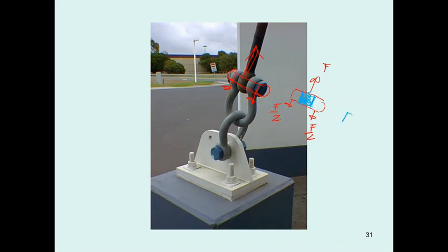And if we cut the bolt at this portion and this portion, and then redraw the free body diagram of this part of the bolt, what we have is the force F. The force F must be resisted by some kind of resistance occurring on this portion also, and we know that this is going to be the shear, and this shear is going to be equal to F divided by 2. So this condition is the double shear.